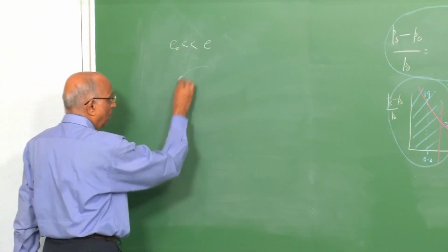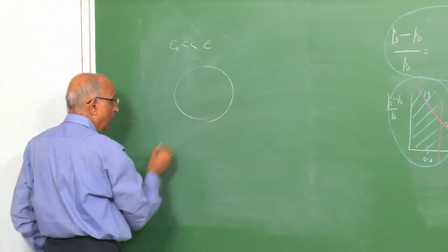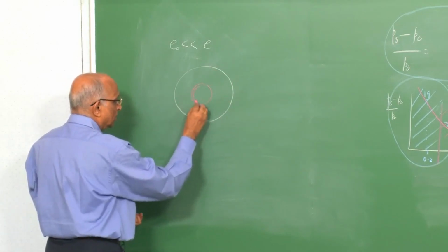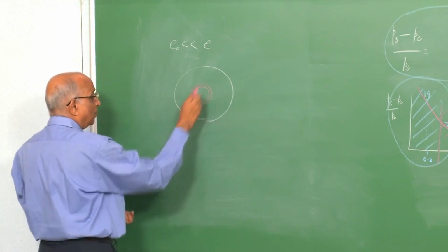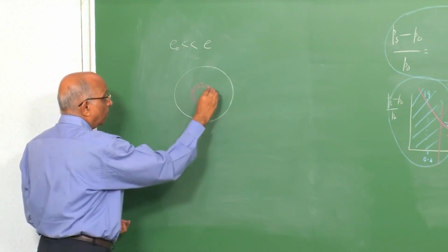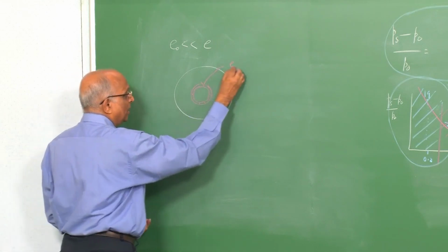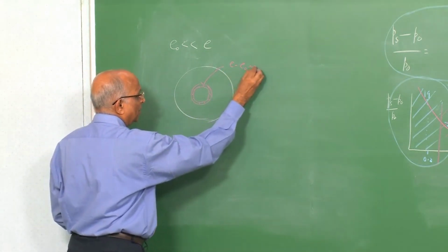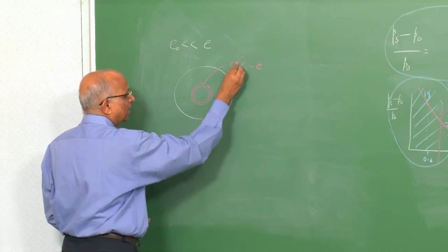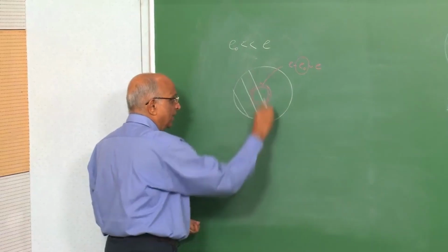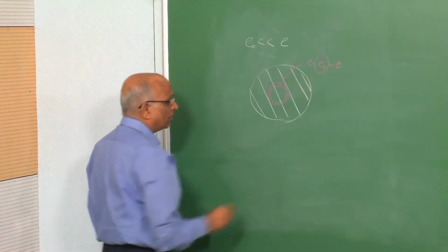Rather, you will recall we had a spherical blast wave, we talked in terms of a small segment, a small annular area, a spherical shell over here, in which we said E minus E 0 is equal to E. That means we neglected the value of E 0. That means, what is it we have neglected? We have neglected the internal energy of the medium here.